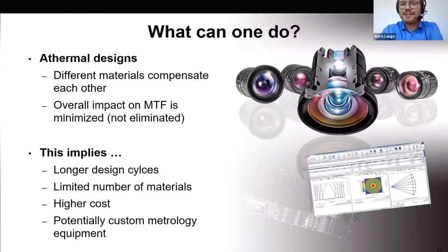a temperature spec. And then very often I personally get to see a temperature spec like operating temperature, say -10 to 60 or even smaller, 5 to 40. And every time there's a sentence below that that says optical performance is not supposed to change. And this is really just physically not possible. It will change. The question is, how much are we allowed to change it?